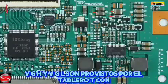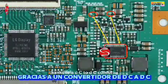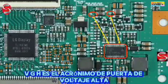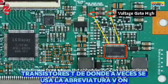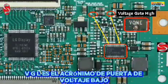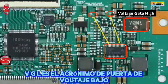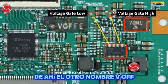VGH and VGL are provided by the T-Con board thanks to a DC to DC converter. VGH is the acronym of voltage gate high. It is the voltage of starting of the TFT transistors, from where the abbreviation V on is sometimes used. VGL is the acronym for voltage gate low. It has a negative value and is used to turn off the TFTs, hence the other name V off.